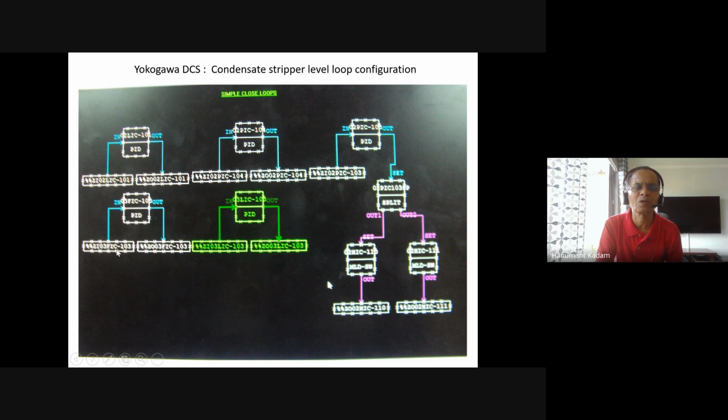You see, this is one closed loop, this is another closed loop, and this is a third closed loop. So in, out, this is the field tag, and this is another closed loop, FIC10, in, out. You see here, this is the input side, this is the output side, and this is your PID block, PID block, PID block. Splitting actions here in the PIC, the action splits.